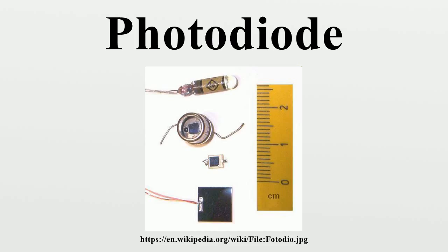Pinned photodiode is not a PIN photodiode. It has P+, N, P regions in it. It has a shallow P+ implant in N-type diffusion layer over a P-type epitaxial substrate layer. It is used in CMOS active pixel sensor.